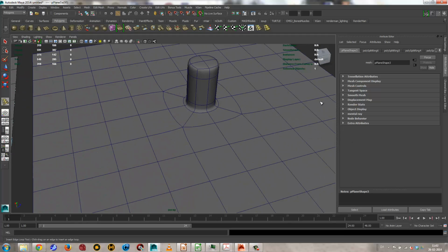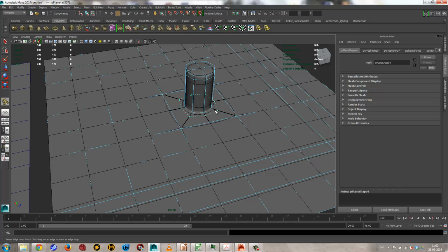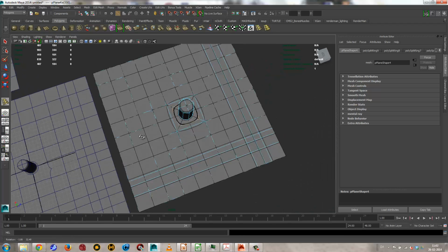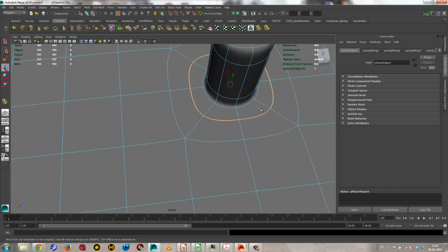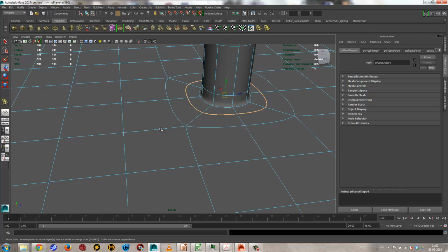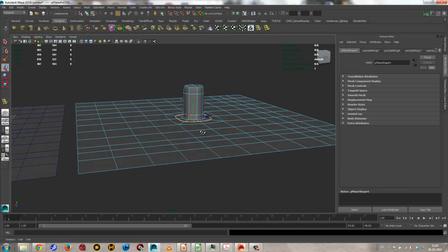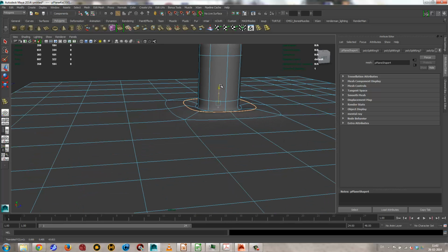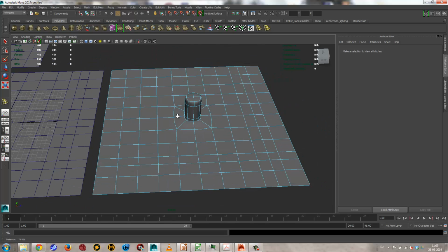Over here, on the other hand, I can do the same thing, add a line here and add a line here. But if I click down here, I'll actually get a line going around because I reordered the way that my curves flow. And this is a very efficient way of working with polygons, because often you'll get to select a lot of polygons, but this way you can create lines that will flow nicely, and also you can select them. So if I double click an edge here, you can see I'll get all of the edges that are part of that loop, or in here where it goes all the way around, and then I can start to work with that to change maybe the shape of it, maybe scale it in to create a different type of look and feel.